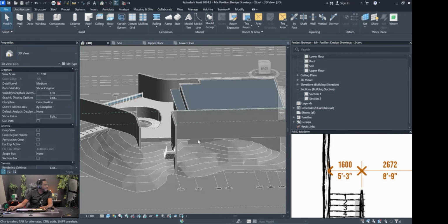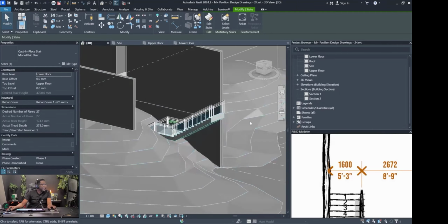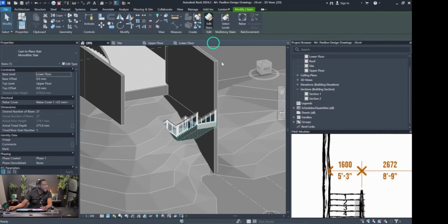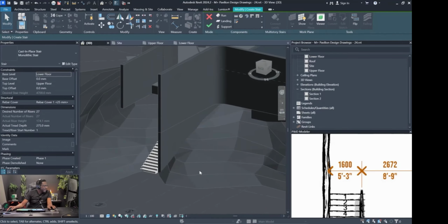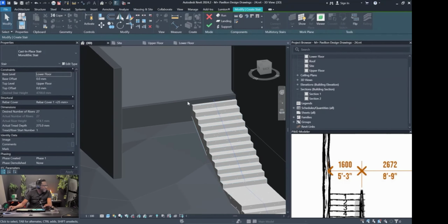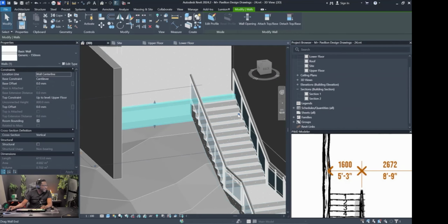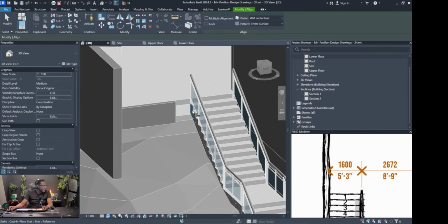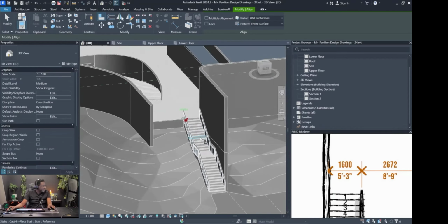So if I look in my 3D view, yes, it's going to be turned the other way, but that's fine. I'll just click it and say edit and flip. There we go. All right, that's looking okay, and we can edit the terrain to match if we need to. We're going to choose OK, and we're going to adjust this wall. We're going to use the align tool. All right, there you go.